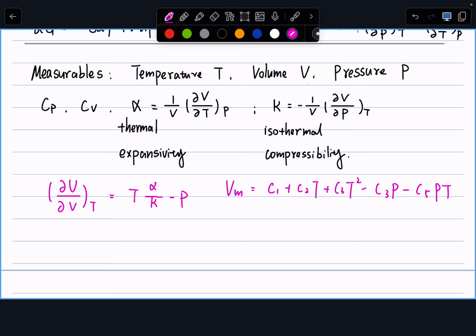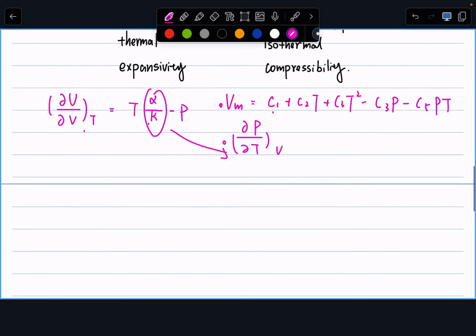We may change it. This one is long, but nevertheless, the idea is that with this equation of state, we can solve for the property alpha over chi, which is effectively equal to the partial derivative of P over T at constant V. We also went over this derivation using the cyclic chain rule and writing the alpha and chi definitions together. Using the equation of state, you can solve this partial derivative, and then plug our expression back into the equation here.